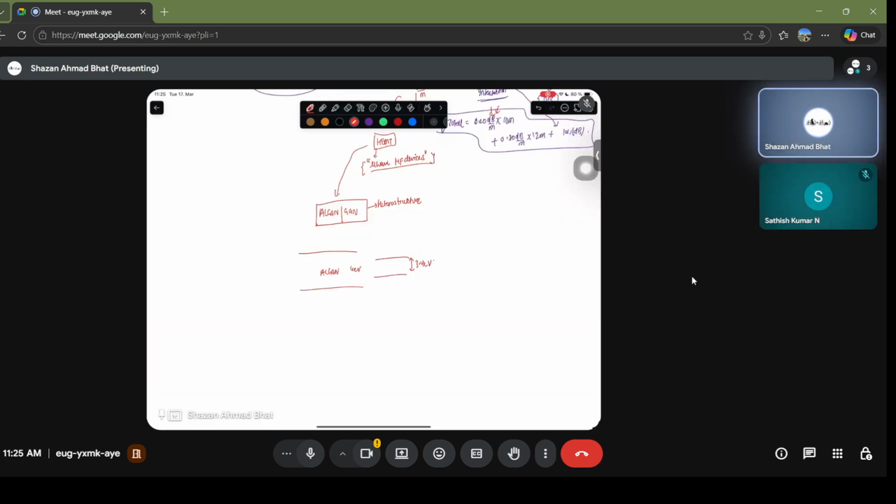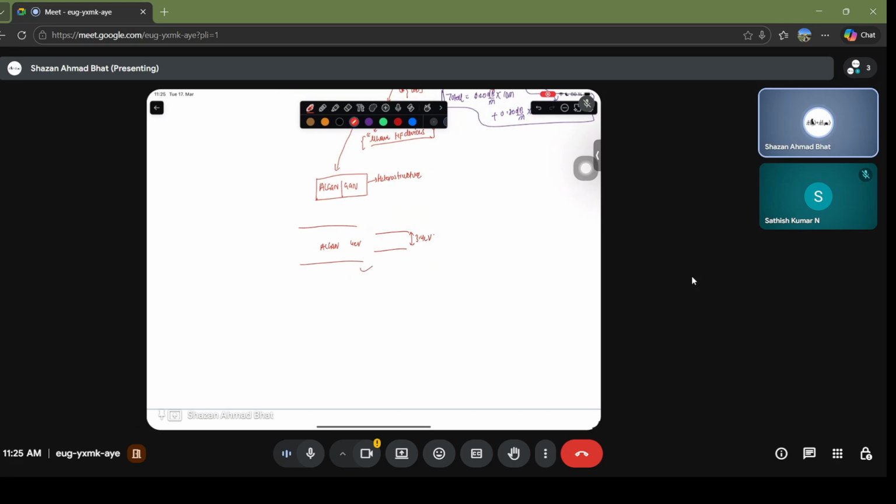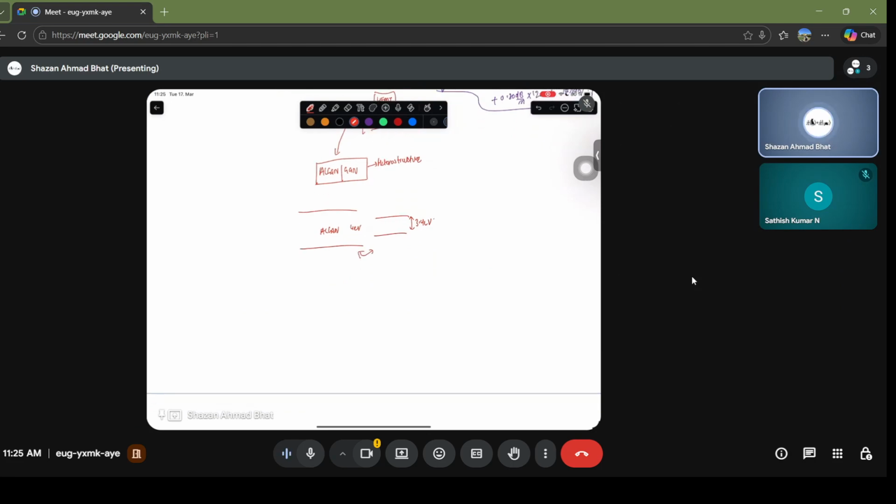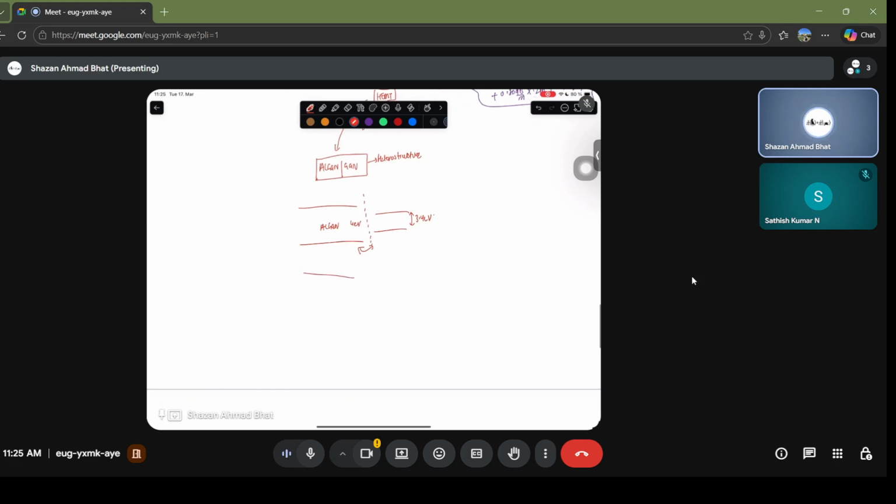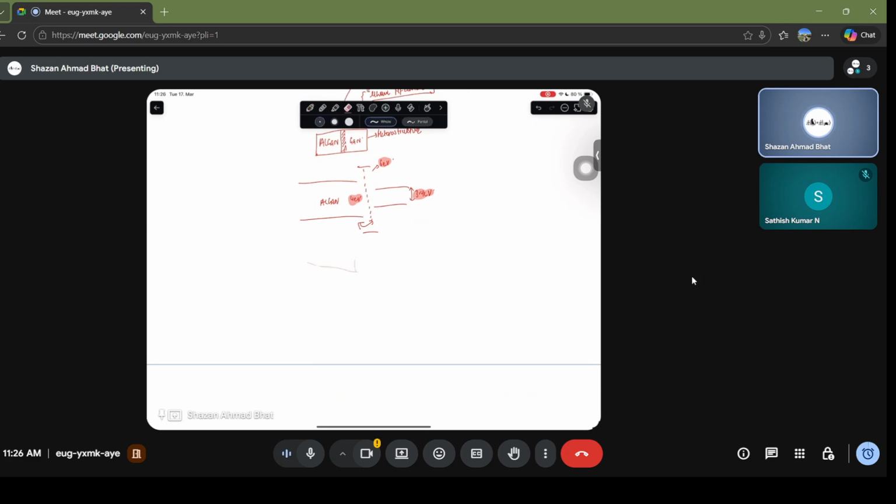And what basically happens is that when you combine these two in such a way that there is no other spacer material in between, it forms a system which looks something like this. Or, in most of these devices, you have another layer, an aluminum nitride layer, and then you have a gallium nitride layer. Aluminum nitride has a band gap of roughly 6 electron volts. So when you combine this system, with band gaps of 4 electron volts, 6 electron volts, and 3.4 electron volts, you get a system which looks something like this.